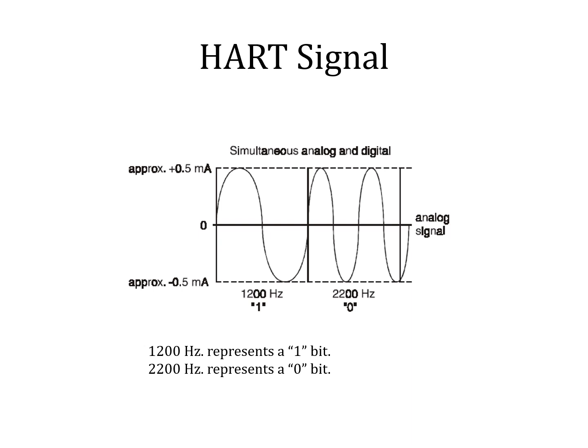Let's have more description about this signal, that how we can plot this signal so that we can conclude in terms of its wave shape also. Now, as I've already told you that peak to peak value is 1 milliampere. So it means across the zero line, half milliampere is on the upper side and half milliampere is on the lower side. So it is a symmetrical sinusoidal signal.